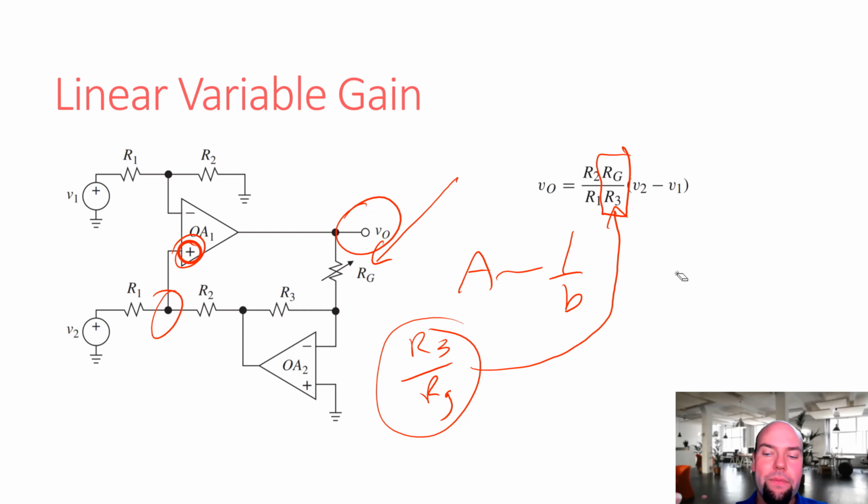So anyway, this is one way to achieve linear gain, and this works for almost any op amp network. Anytime you just intercept the feedback path and scale it, it's a way to achieve a linear gain control. Being careful to note that if you're using an inverting op amp topology, you have to feed back to the other terminal of the op amp. You've got to flip the op amp. So, okay, that's kind of neat. Cool.